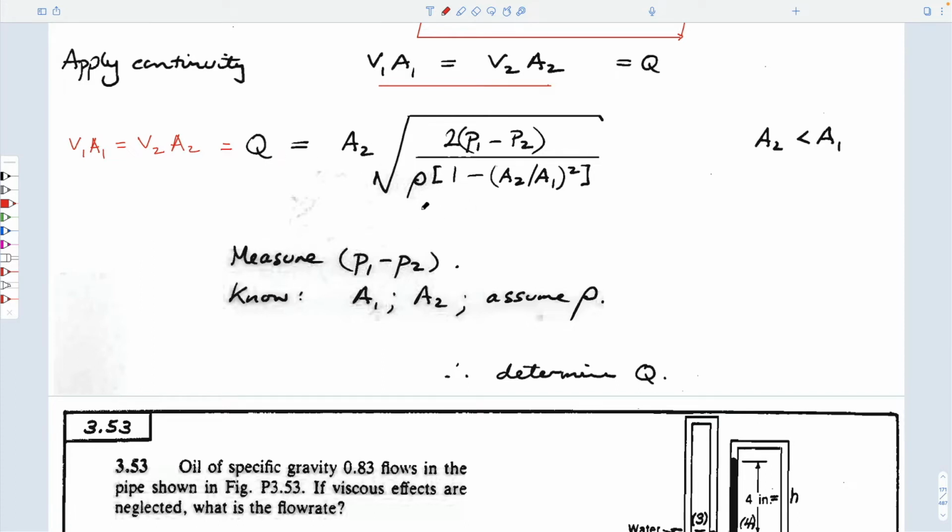So I suppose if that's the case, you could surmise that this parameter in brackets is actually V2. And if you measure the differential pressure, not the absolute pressure, the differential pressure, you can get, with a correction factor for the areas and the density of the fluid that's flowing, you can get the flow rate. That's it. Nothing more involved in this.